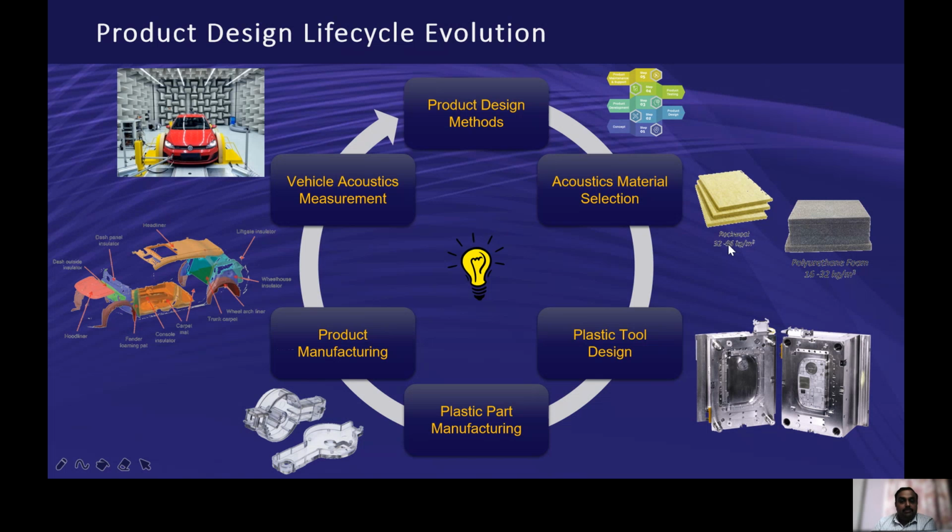So, developing an acoustics material. When you come back to the product design of your substrate, this is an injection tool where you have the core and cavity, and this is the profile which you get as a finished part once the injection molding process is completed. You can see here the finished components being manufactured using the injection molding machine, which ranges from 50 tons to 4,000 tons, right from manufacturing PET bottle caps to manufacturing bumpers and dashboards.